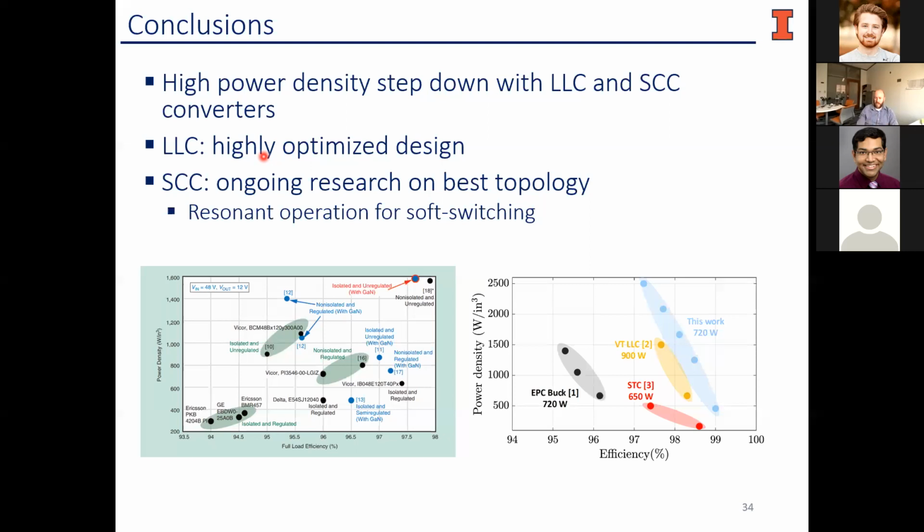the lifetime. And so from that standpoint, what some of these have shown is the temperature rise, right? They'll show what the operation looks like when they're operating at their peak power. And all of these converters are efficient enough that they don't need heat sinks, or at least they claim they don't need heat sinks, and they don't need air flowing across them, right? And so if we were to normalize all of these at a specific power level, and normalize the airflow and everything else along those lines, what I think would be a very good indication of reliability would be those thermals, right? What is the hottest component? What is that delta T rise that we see? And that will give us a good indication, right?